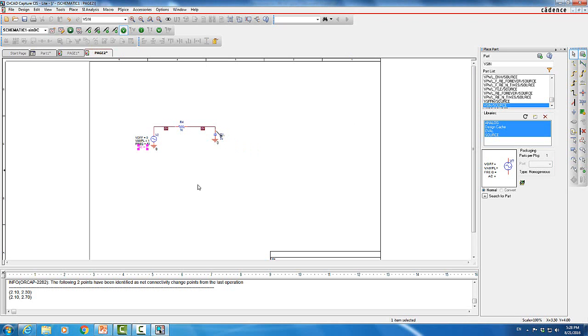You can use the sine wave voltage source in ORCAD to do both transient and AC response. Basically, if you put the AC value here 1, you can do AC sweep, and at the same time you can do transient analysis and look at the response of the voltages. In any case, here we're gonna do a transient analysis, or time domain response.